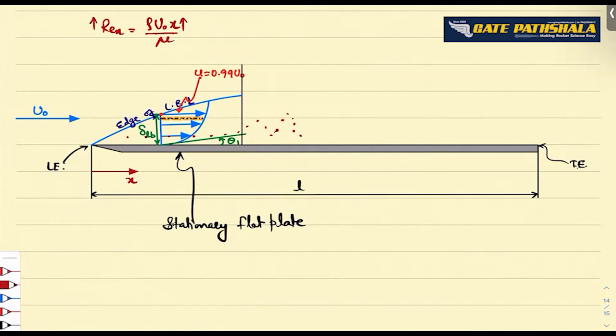So instead of going in laminas, they will start to go in zigzag manner. This small region in which they do so will finish here. After that, they become completely irregular. This is a region in which the particles will become unstable. The structure which was stable and the fluid was flowing in laminas breaks completely and becomes unstable and completely irregular after the second black line.